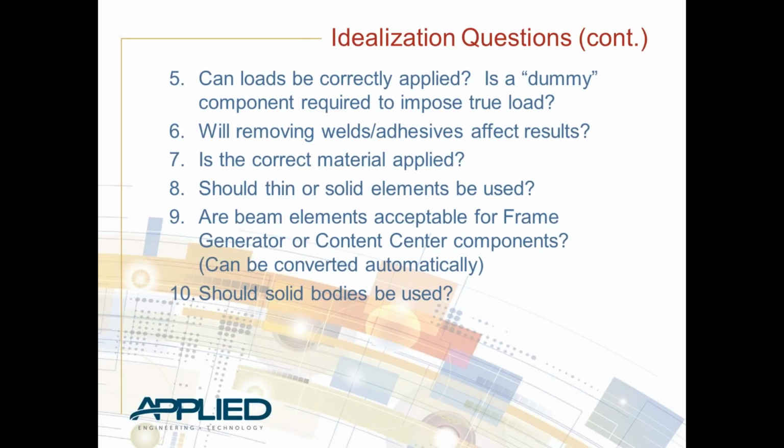That's something you have to think about within your model. If you've got some complex geometries in there and the load is applied in a different direction, or it's rotational or whatever it might be, think about whether it would help to put in a dummy component to simplify my model, but still apply those forces through something else that we can add, to verify or make our results a little more accurate.